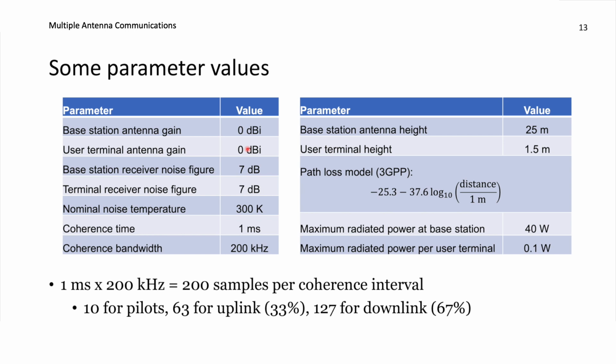When we are computing the noise variance, we need to consider the temperature. That is giving us the ideal noise variance, and then we need to add something called a noise figure to that number, because that is describing the noise amplification that is going on inside of the receiver as compared to just the fundamental thermal noise that will exist.